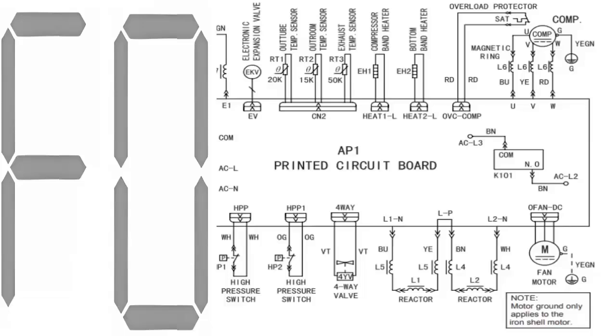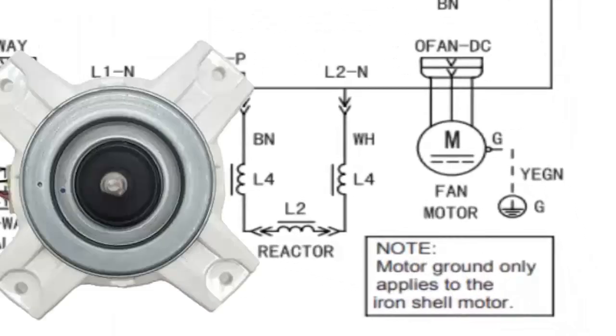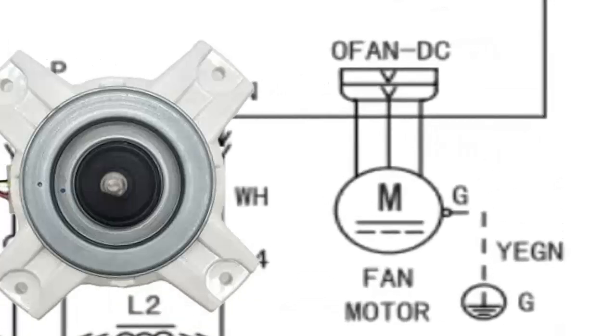8. When the error code indicates an issue with the outdoor unit motor, the electronic fan control is located on the external electronic board, not inside the motor housing, which is why the fan is powered by only 3 cables.